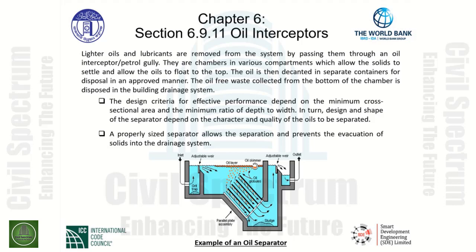From the parallel plate assembly, due to the velocity of water flowing through, we may have heavier sludge particles that will settle out in the bottom of the tank and allow clean water to rise up in the third compartment with an adjustable weir again to adjust flow into the outlet of the oil separator. This is a simple process of capturing the oil particles accordingly.